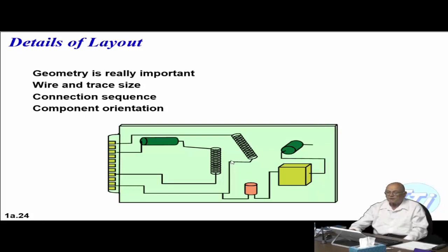Now, one of the problems you have with PC cards is autorouters. You can almost say that an autorouter maximizes the EMC problems. Because what they're typically trying to do is save space, save material, like minimize the amount of copper used on the board. Well, you'll find out that you should maximize the amount of copper. Keep your ground planes where there's less space between them, because it creates a smaller loop area, as we call it.